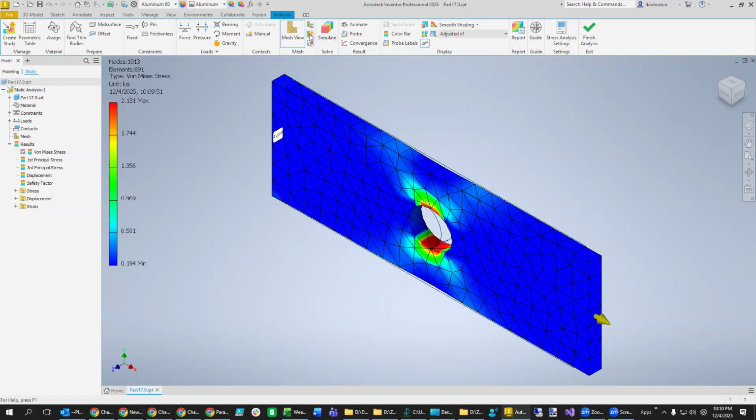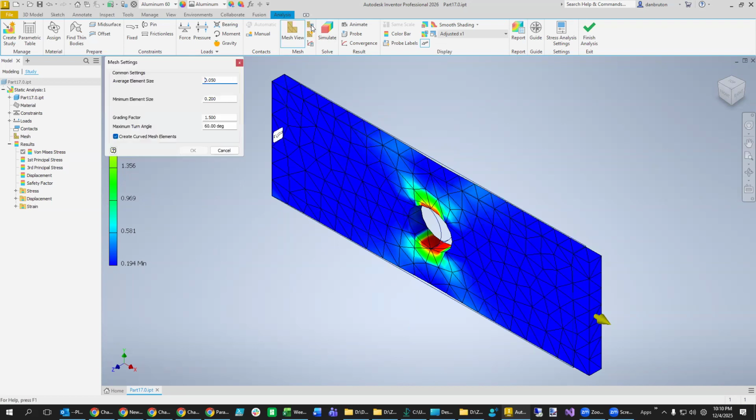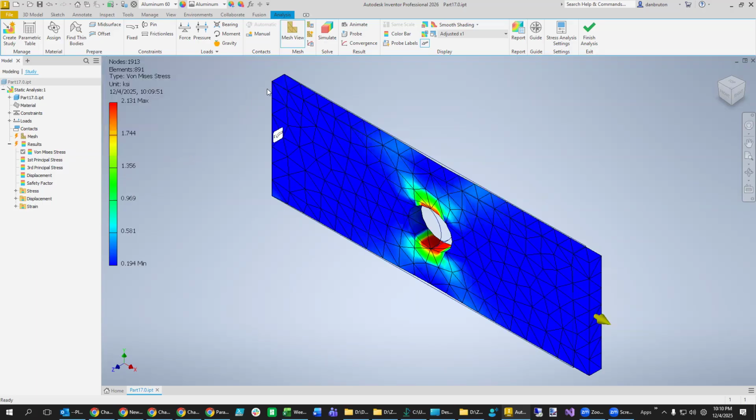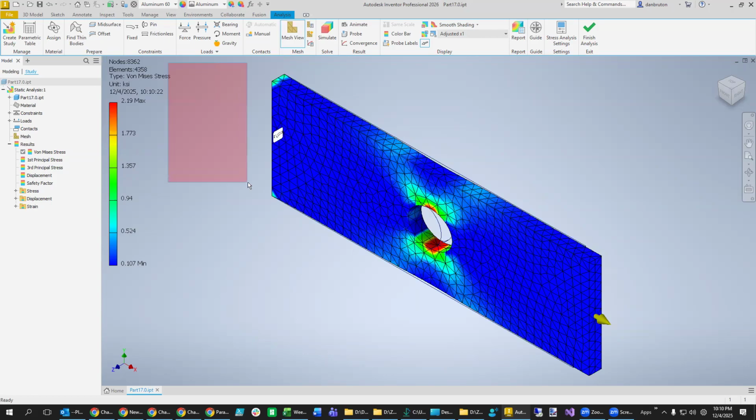I think there was a way, mesh control. Okay, and you can see this one's going to be, I think, closer to the value that you have. I'm going to go one step further and just go to 5 like that to show you that if you run the simulation now, probably take a little bit longer. Well, not that much longer. And we got a little bit of convergence happening on the maximum stress where this red point is right there.